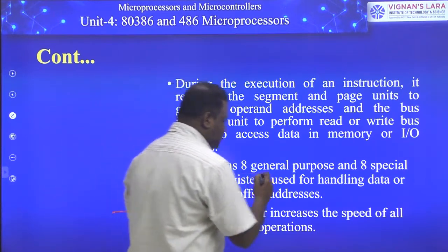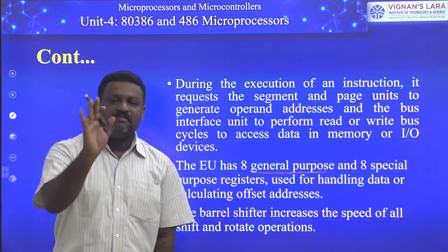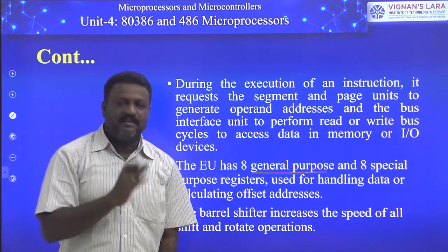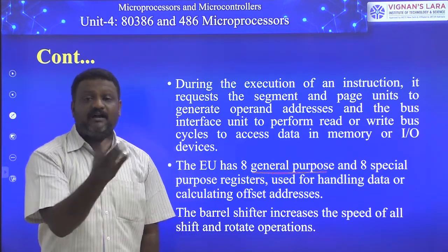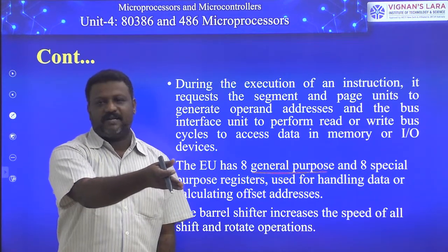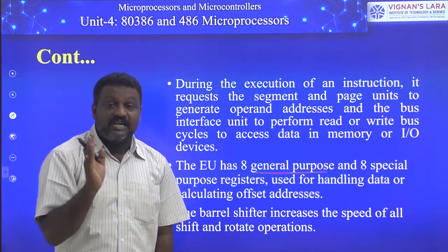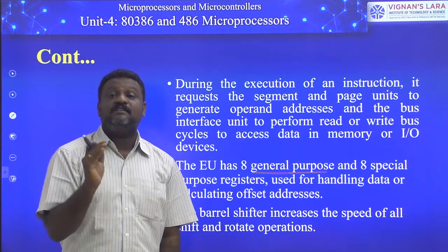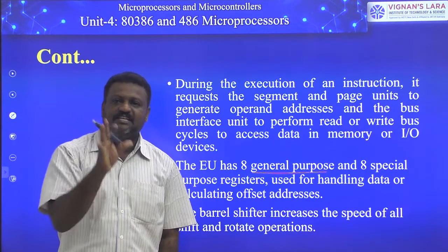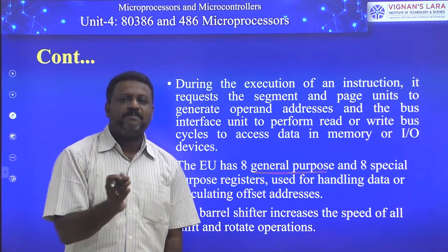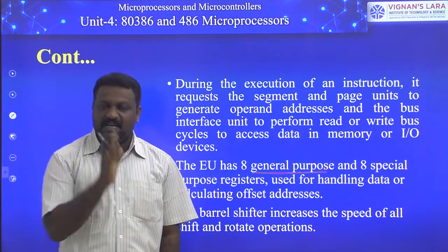What are GPRs? This is very important, guys. What are general purpose registers? You remember, friends, if you want to call a register general purpose, the register is suitable to hold either data or an address or results temporarily. That means the usage of these registers purely depends on user interest. Such registers we consider as general purpose registers. And one more thing, in so many processors you may identify that the general purpose registers we can call the scratch pad of that corresponding processor itself. That you have to remember, friends.